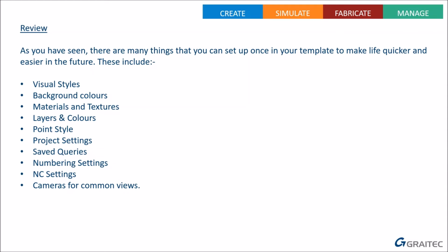With the layers, I've created some extra custom layers so that I can put my construction lines on a construction layer and hide them later without having to interfere with the standard layer. And I've got a layer for glass, so when I move things to that layer, they look like glass and not like any other steel plate.